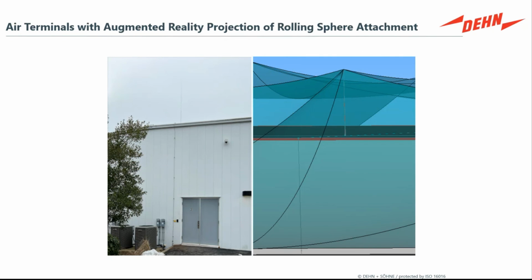Although it's not ideal, you may have down conductors that are near doorways, and then of course you want to properly mark them. But this is a nice illustration of what you would see if you had that electrogeometric coverage model built over the structure. And here you can see the walkways and the areas around the doorways are all adequately protected from lightning, protected from direct strike.